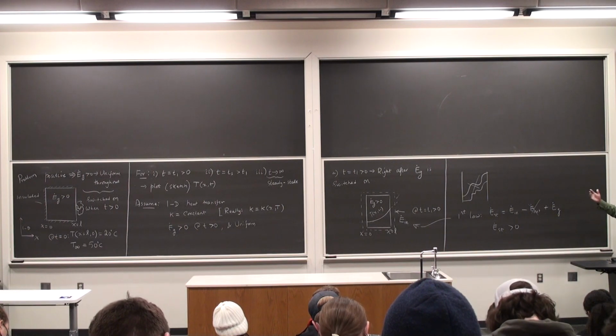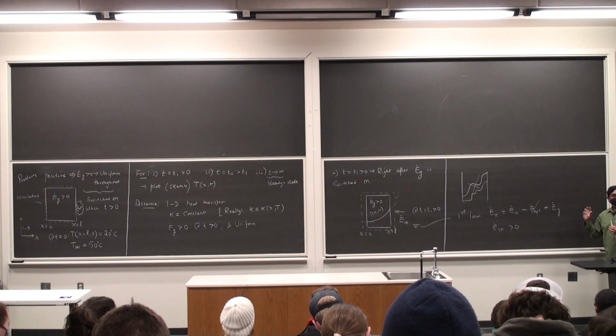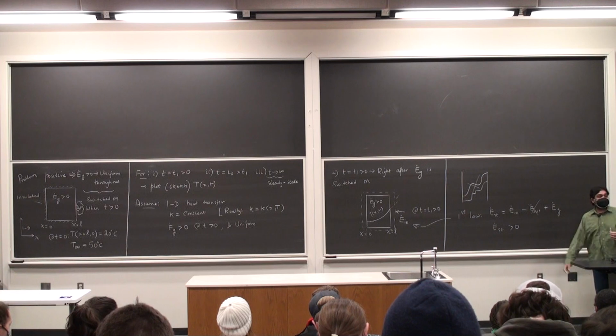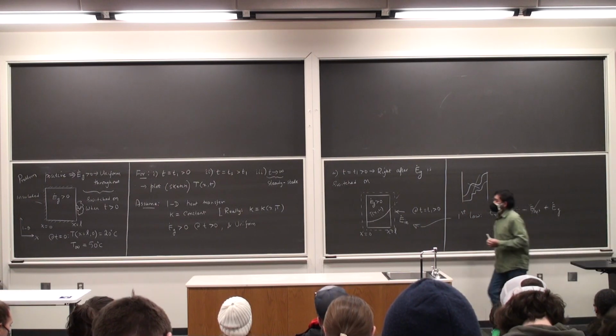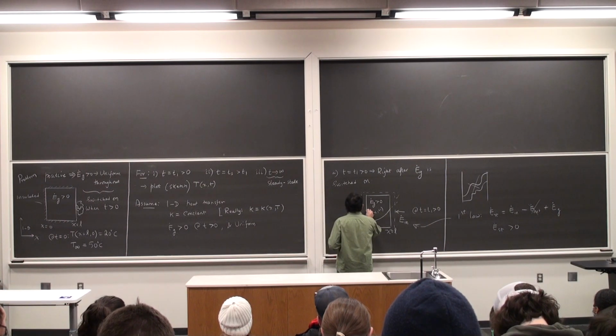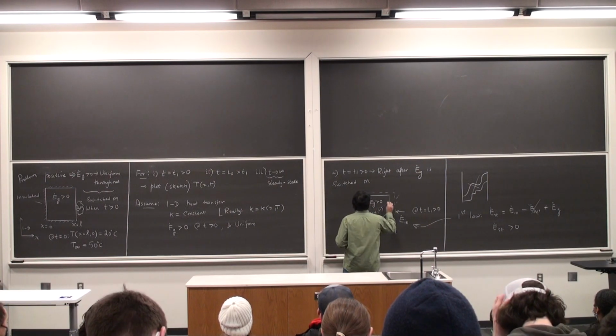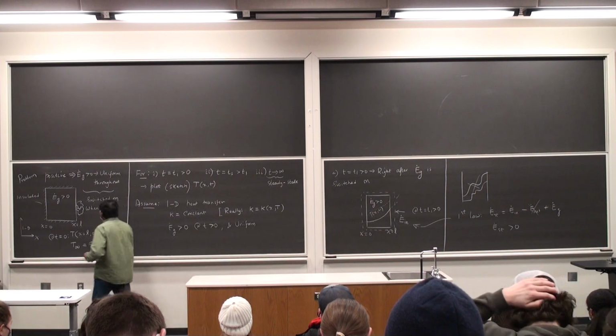So at the next time instant, this situation will continue. Maybe the slope at x equal to L will be a little lesser in magnitude, because you see that the temperature on the right side of the wall has now increased a little more than before, but I'll still continue having this profile for some time. Maybe the next instant in time, a slightly lesser slope at x equal to L.